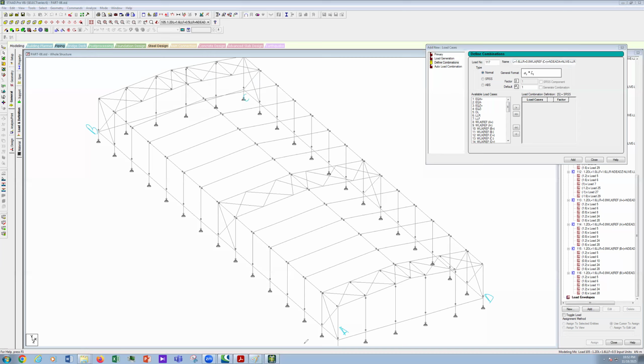So for point A, the wind load is following these directions, okay, but for C, the wind load is going in this direction, and similar for D, this direction and this direction, okay, you can see it is negative X. You can see here that along this direction is positive for X, okay, but the wind is following the opposite direction, so this is minus X, okay.